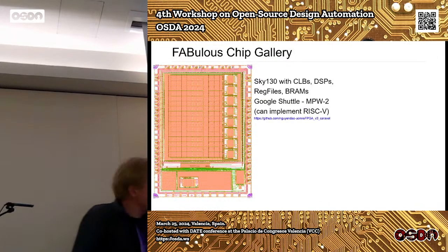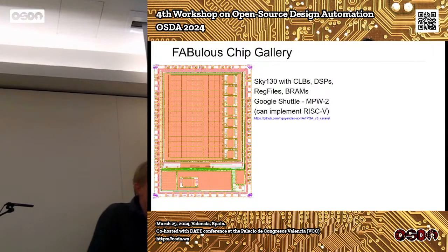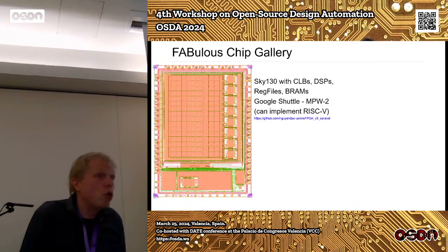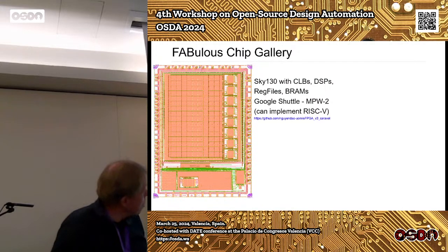Our first chip wasn't the first one. The first one was a TSMC 180. This was the first chip in 130 nanometer, LUT5s as well. Blocks at the right, we have actually block RAMs. They are 1 kilobyte. You can program different aspect ratios for width and depth.